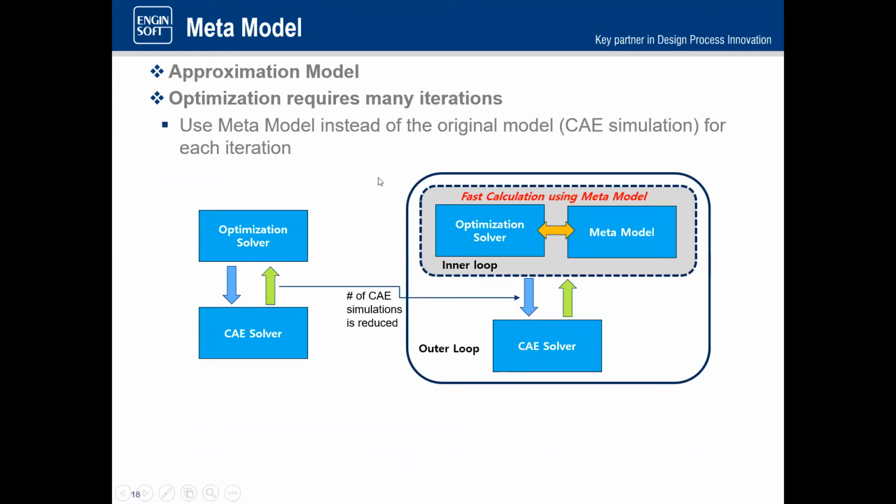So how does it do that? Basically the idea of the meta model is it represents an n-dimensional design space that's mapped to all the design variables. So you run the DOE, and the DOE results are used to come up with the n-dimensional meta model. And then once you have that, you can optimize with the meta model and find the optimal point.